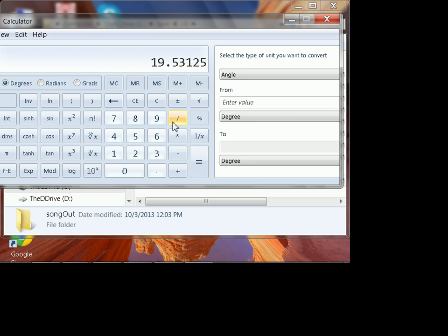You're looking for a number like 5,000, so to get 5,000 out of 19, you're off by 2 orders of magnitude. You need about 100 times gain from a microphone preamp before the analog audio input is going to give you anything.